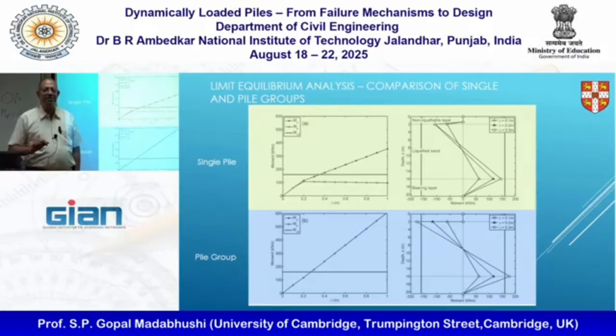Now that is way beyond where we are for piles. Normally, when you're doing pile design, if they formed plastic hinges, you'd say tata bye bye, the pile has had its day, right? However, more recent British standards and probably Eurocode as well are allowing plastic hinge formation in retaining walls, steel retaining walls.